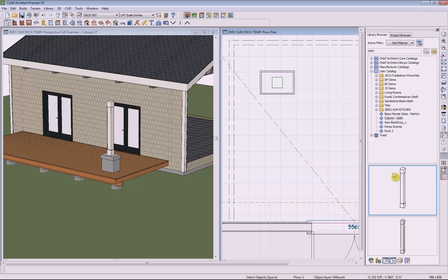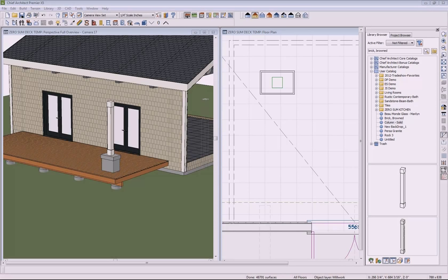And at this point what we want to do is start to replicate that post over and get that set into place. Before I start to replicate the column, I think I'd like to add some colors and materials on there. So on this base that we've created on our side here, we want to change our colors and materials. So the first thing I want to do is change this capstone here to a black color. So I'm going to go up and grab my material eyedropper and pull up the color from our door and just click to add that onto that capstone.